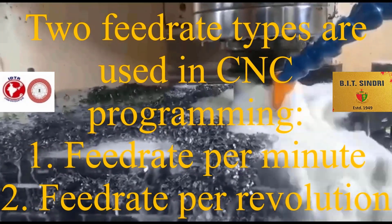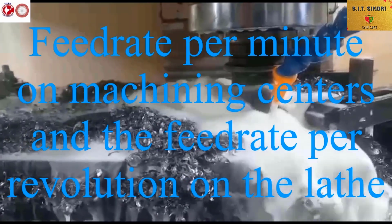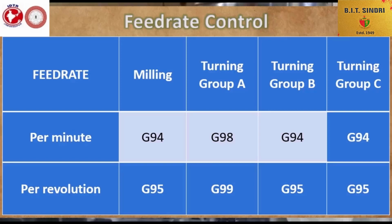In practice, it is much more common to use feed rate per minute on a machining center and feed rate per revolution on the lathe. There is a significant difference in the G codes used for machining center and lathe.